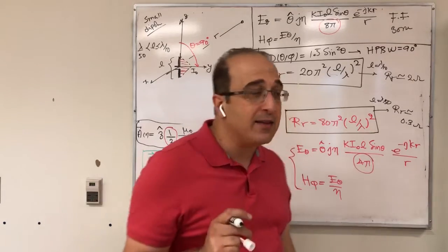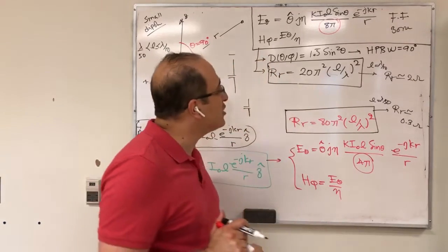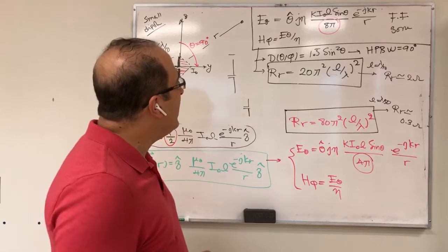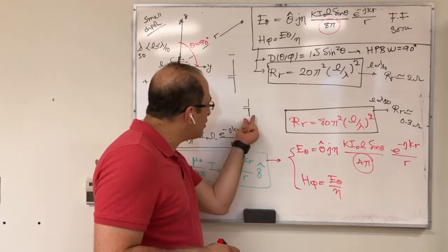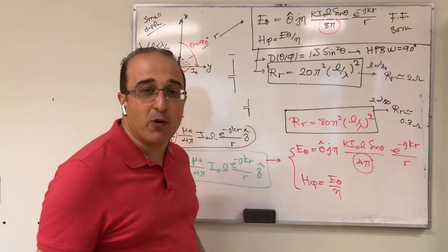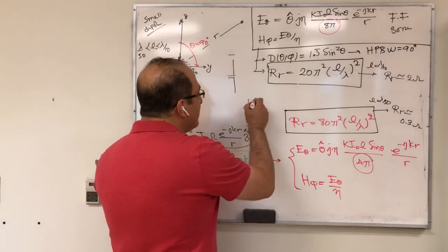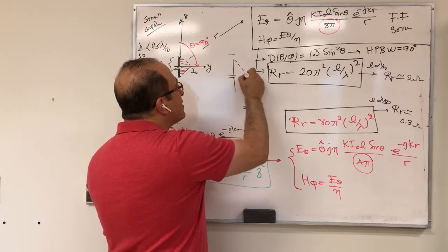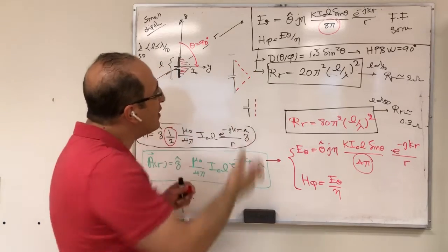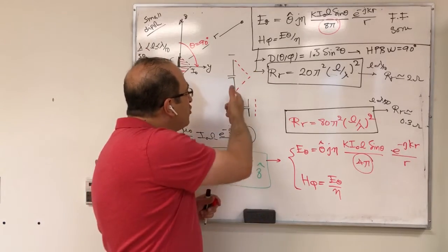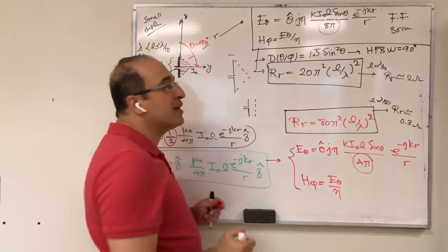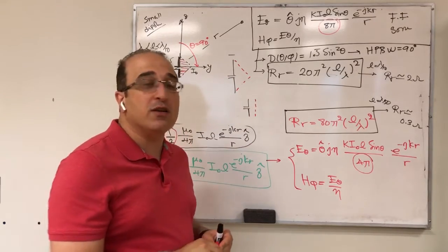The reason that this does not show in the mathematical expression is that we helped the infinitesimal dipole antenna with top loading. If you look at the current here, this was uniform, this was triangular. So we weren't comparing two of the same thing. This current distribution and this current distribution were different.